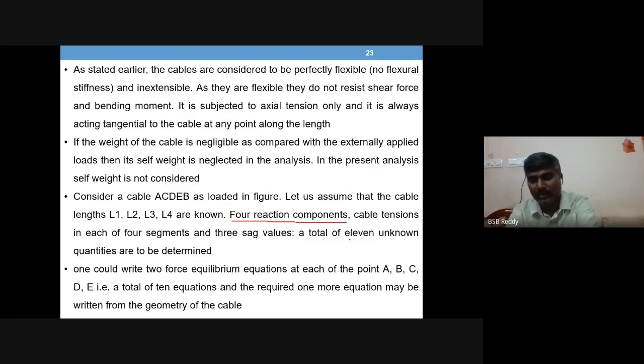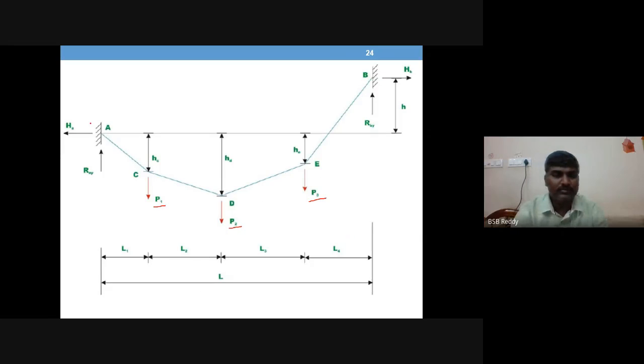Unknowns are now counting here. You are counting the unknowns. So 2 here. It looks like the rigid support, but it is not. Okay, because the cable cannot resist bending. You cannot expect moment reaction. Remember. So same here. Here also, it looks like it is a fixed support, but the cable cannot produce resistance to bending.